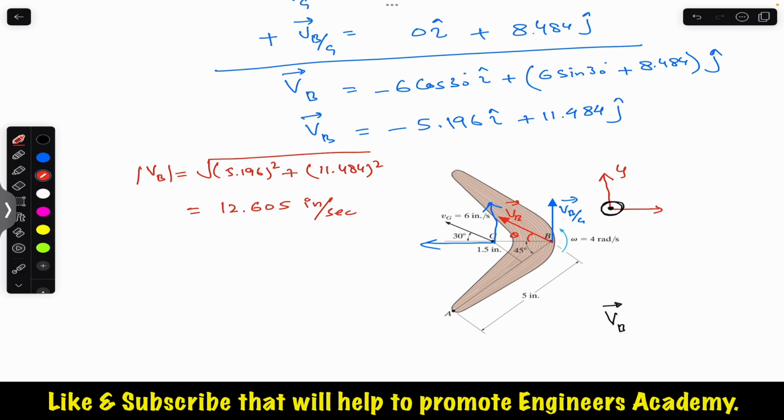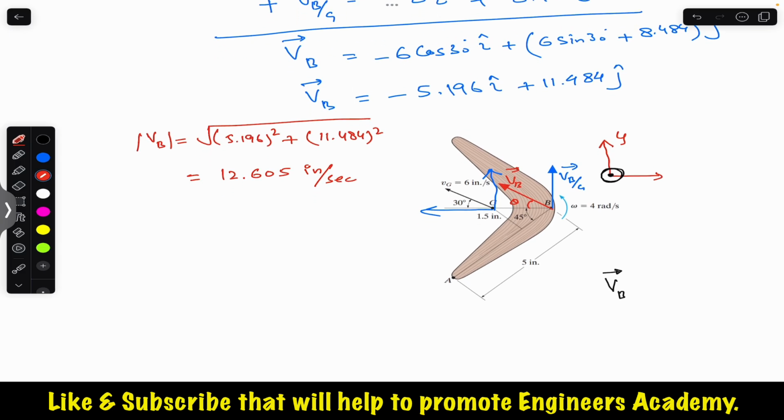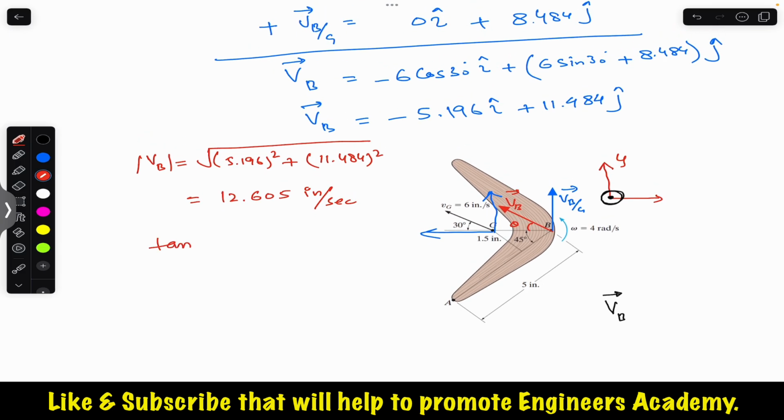And we can find this angle theta as well, which VB is making with the horizontal. So we can always apply tan theta. If we consider this is VBX and this is VBY, then tan theta will be VBY divided by VBX. So VBY is 11.484, divided by 5.196, and taking tan inverse, we will be able to find that angle theta.